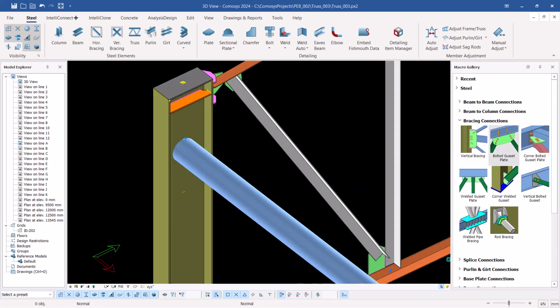So I'm going to pick on that and pick the column and pick the tube and right click, and I'll be able to go back and just type letter M. And I forgot one thing. I would have just clicked use as a default connection, and I would have just applied it automatically to the rest of the connection.